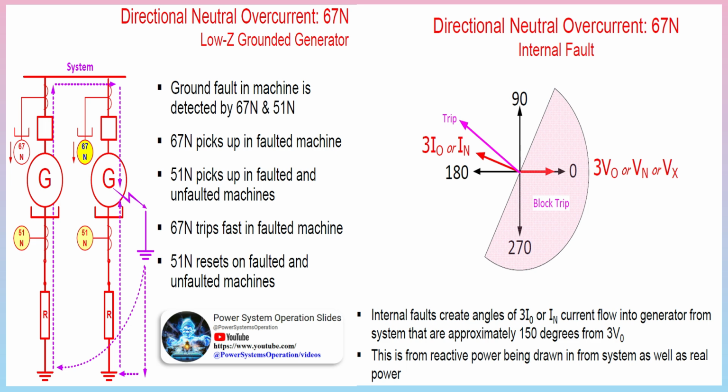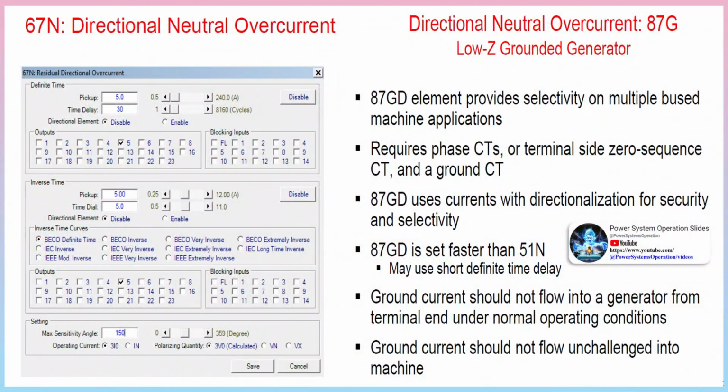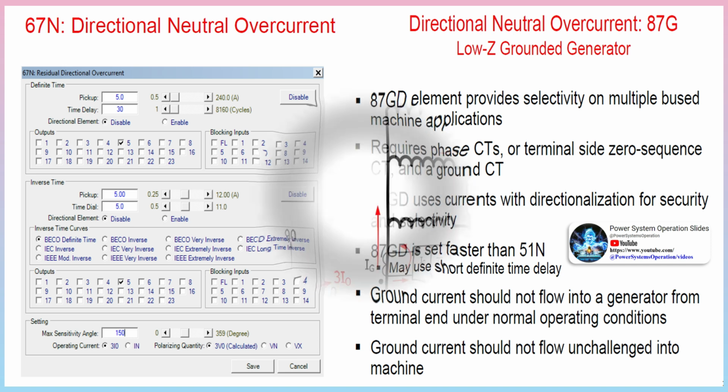A fault near the neutral shunts the third harmonic near the neutral to ground. The result is a third harmonic undervoltage, with security issues for generator operating mode and power output, real and reactive. Stator ground fault, high Z grounded machines: 95% stator ground fault protection is provided by 59 and tuned to the fundamental frequency. It must work properly from 10 to 80 Hz to provide protection during startup.